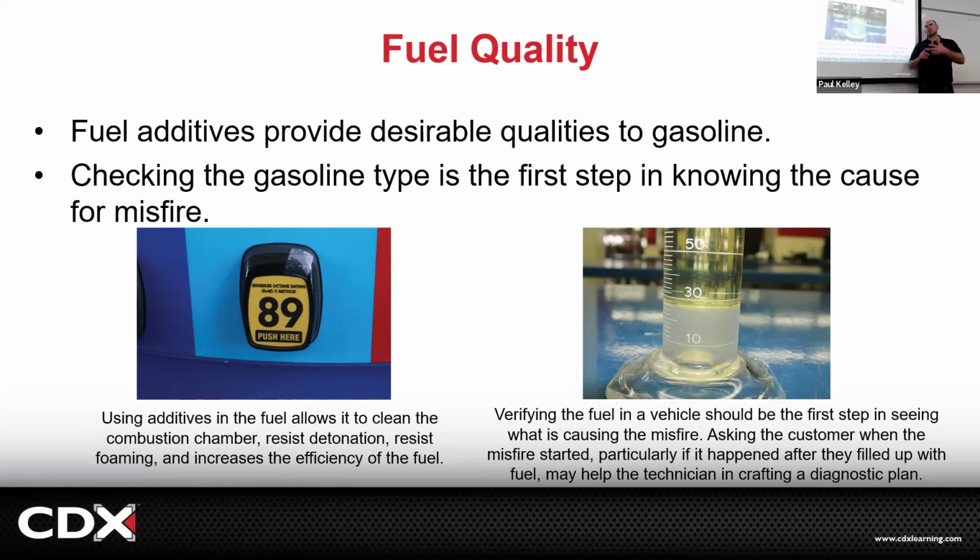Does it have spark? Does it have fuel? Does it have compression? But he told me it was running good. I think I ran out of gas. I put in gas. It smelled weird. It started up for a second, then it died, and now it won't restart.